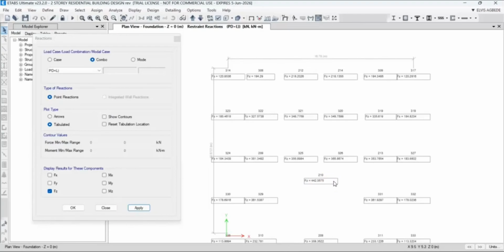Right, so now we are going to get the required footing size to be 2.21 meter square. Okay, so now the square root of 2.21 meter square, meaning we are going to get 1.48, right? That is the length of the footing and also the width of the footing. So the length and the width of the footing is 1.48 meter. We can round this up to 1.5 meter. So your required footing area is going to be 1.5 by 1.5 meter.